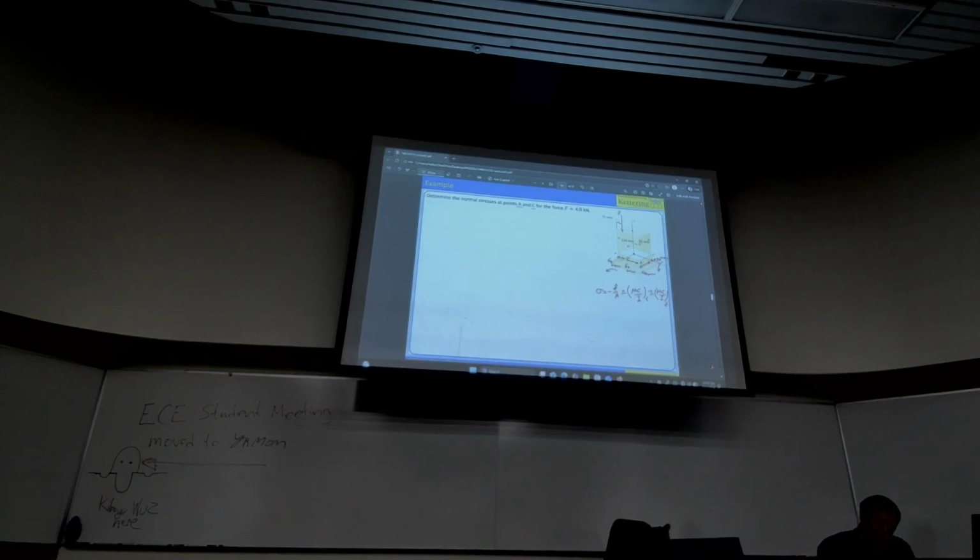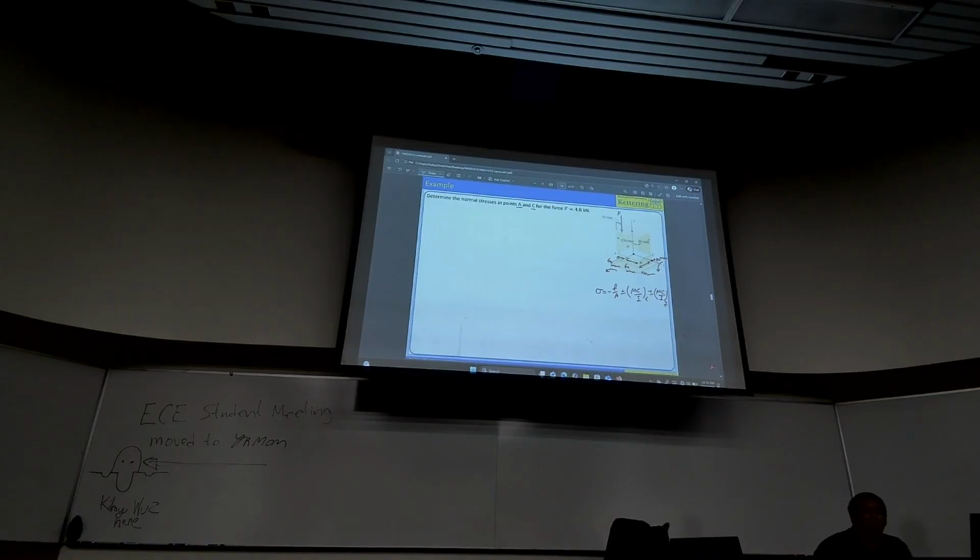About Z also. At most, you have bending about 2 axes, nothing more. Guys, phones aside, please. Thank you. This is for you guys again. MC over I about X, MC over I about Z, and at most F over A. You should not expect more terms than these 3 for sigma.